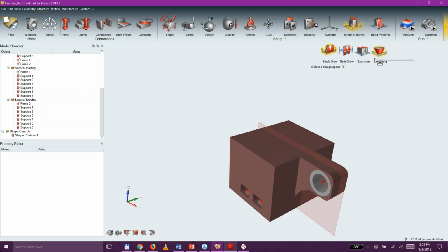Final option here, overhang. This was a new one that was added to accommodate additive manufacturing. I said that you can create just about everything with additive manufacturing. That is true, but anything that hangs out too far, you also then need to 3D print some sort of support structure. And what this does is it allows you to provide a manufacturing constraint that does not require a support structure by limiting what the overhang is.